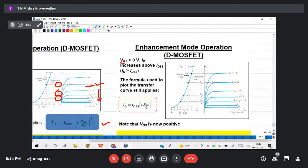When VGS is positive, like +1, then ID will be greater than IDSS. So this is more than IDSS. That is also valid. So though the name is depletion type MOSFET, we can operate as depletion mode or enhancement mode, and the current equation is the same as the JFET current equation.